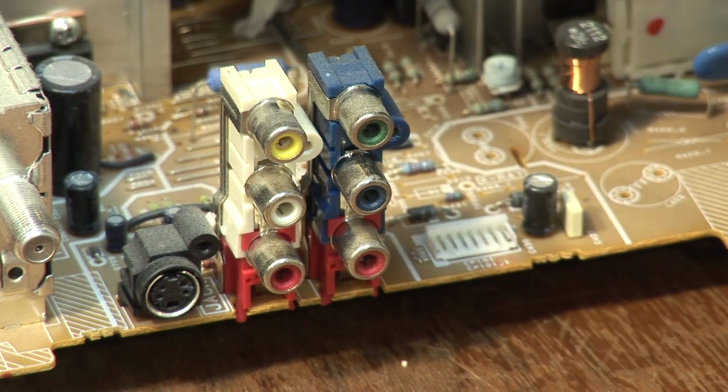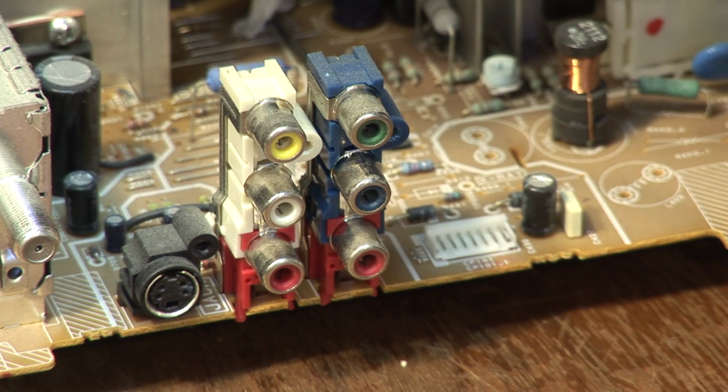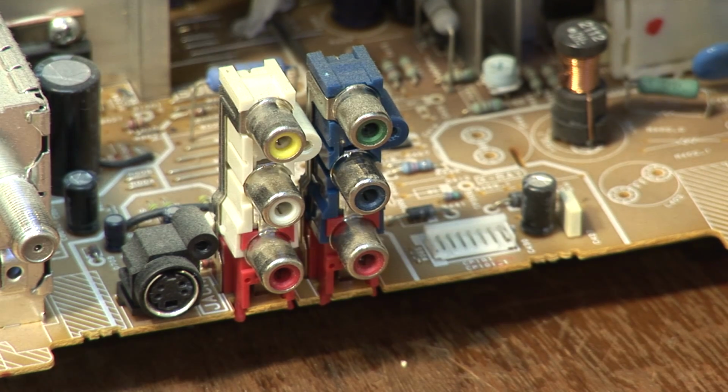One thing I noticed on this TV, this being a late model CRT set, it actually has component inputs, but don't be confused. They're not a high definition input on this set. It is only a standard definition television, but the component input would allow connection to a DVD player. Whether this set would display progressive scan or not, it probably only displays interlaced. Some TVs would display progressive scan, but I don't believe this is one of them. You need a dual frequency sweep set, and they were generally high definition TVs that did that.